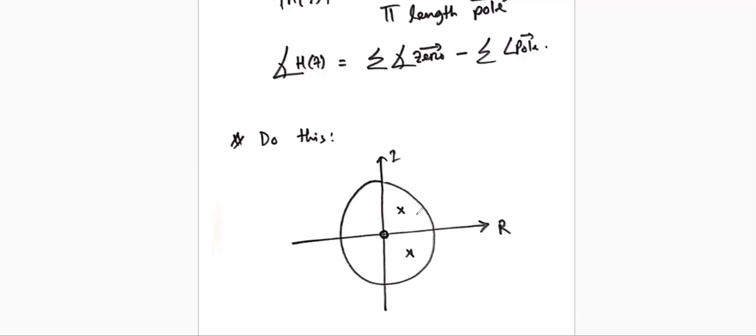If they are outside the unit circle, then we just need to calculate according to the formula, not by using the z-plane calculation. So this is only true whenever the pole and zero locations are inside the unit circle. This is a note for drawing the phase outcome for different values of omega from the z-plane representation.